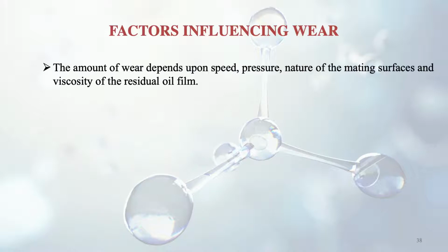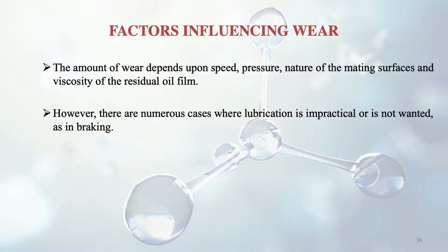The amount of wear depends upon the speed, pressure, nature of the mating surfaces and viscosity of the residual oil film. However, there are numerous cases where lubrication is impractical or is not wanted, as in case of braking. In braking, we don't want lubrication, because lubrication will let the vehicle slide to a larger distance instead of stopping it in a lesser distance.